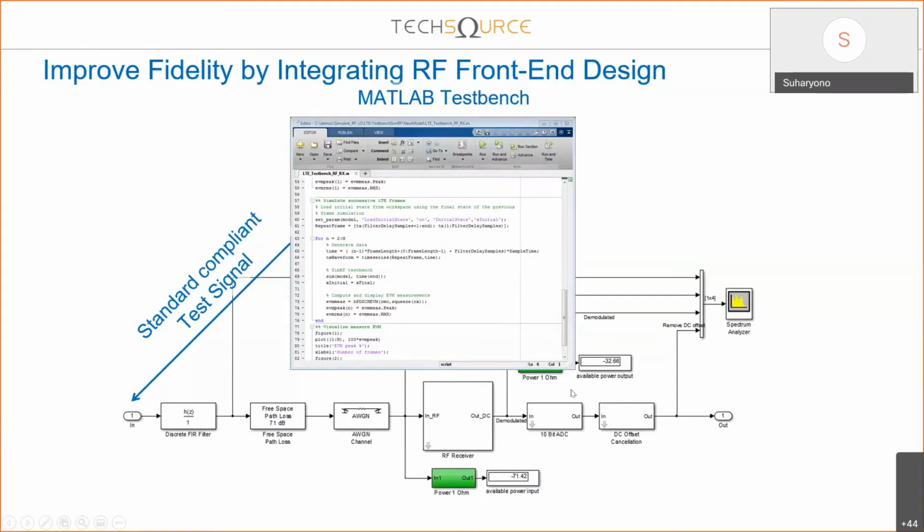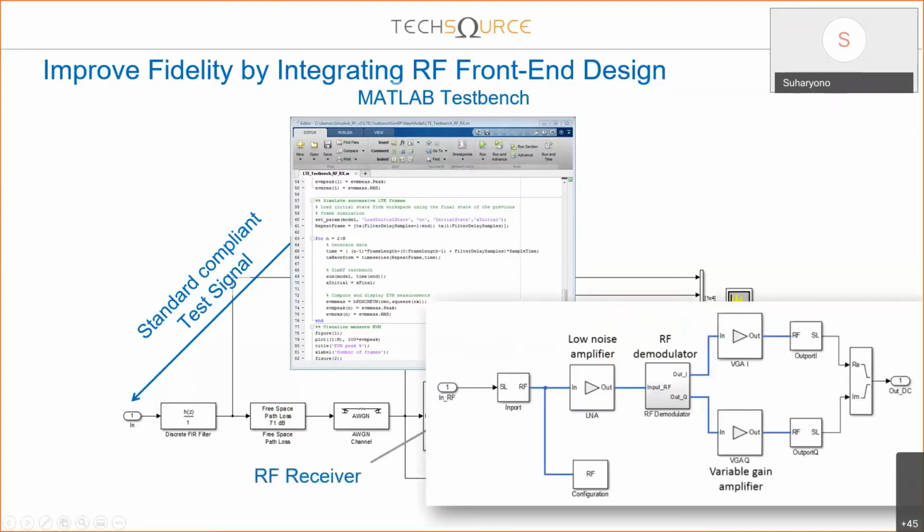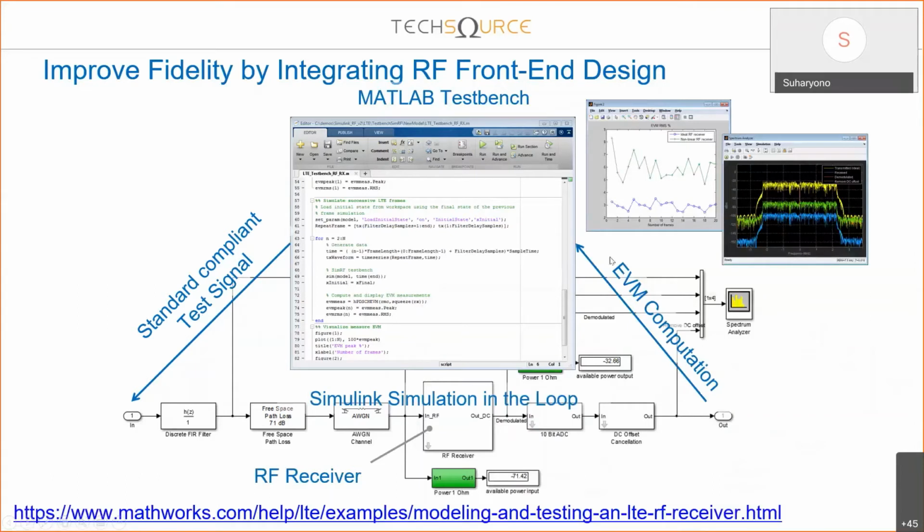The RF front end is simulated using our tools like RF Blockset, which allows you to do closed-loop simulation with the baseband and the RF together. So this is a typical snapshot of your RF portion. Then you can also do analysis like the EVM computation.